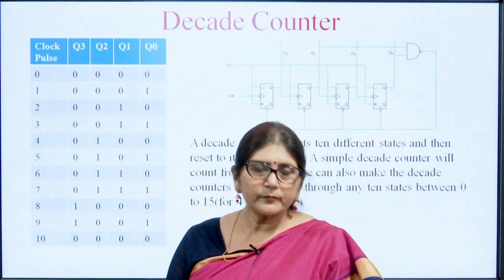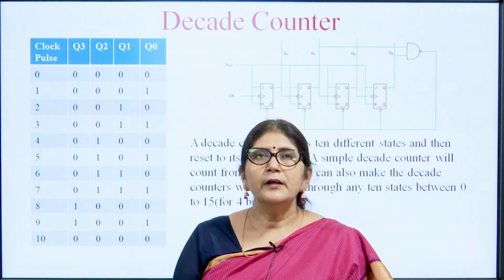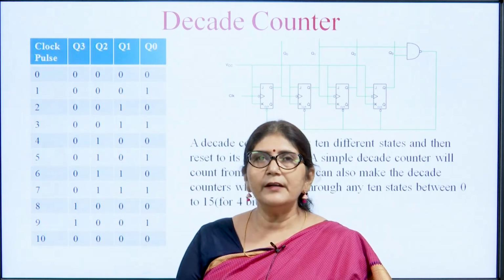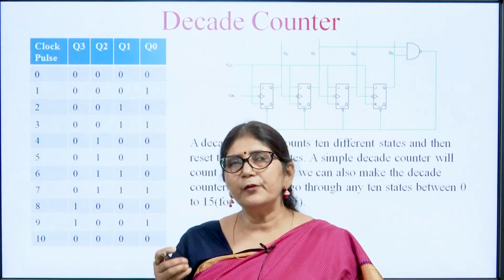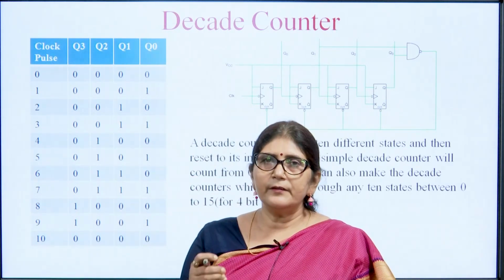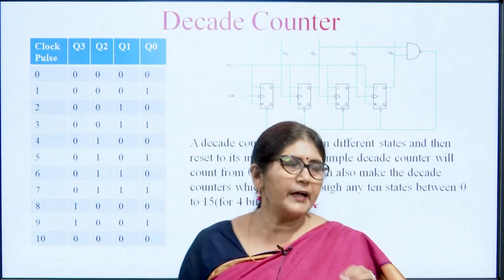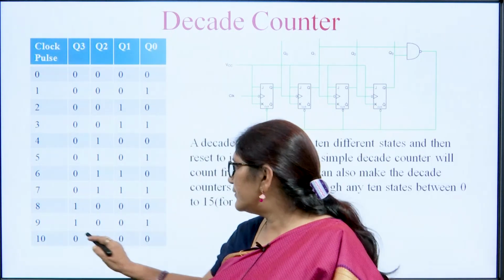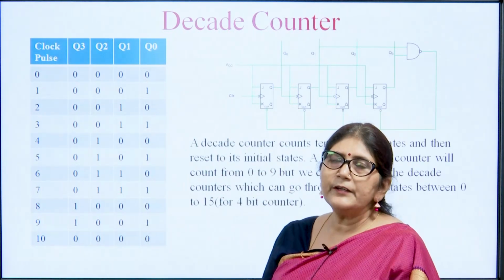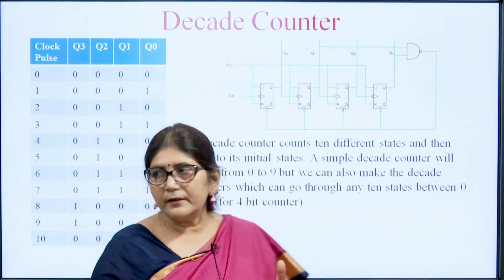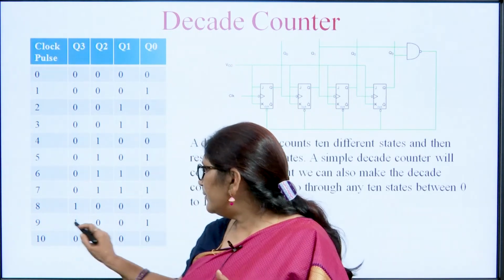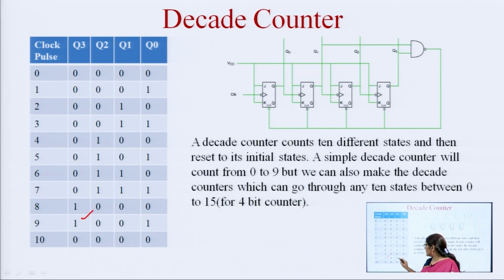Now, the most commonly used counters are decade counters. Generally in any display unit we need to count the numbers from 0 to 9, and when 9 appears, then it should produce 0. So, this type of decade counter is used for this purpose, and here we can see this is 9, meaning 1 0 0 1. So, when 1 0 0 1 appears, then it changes its state.